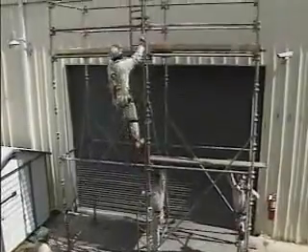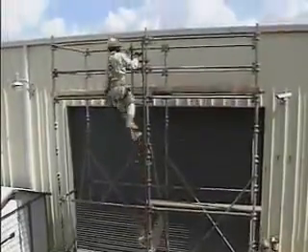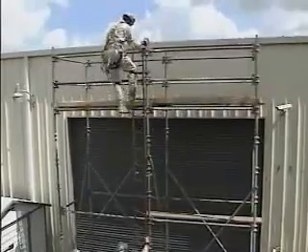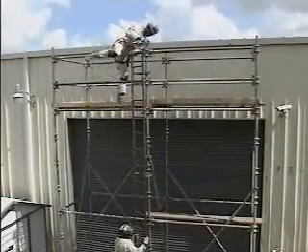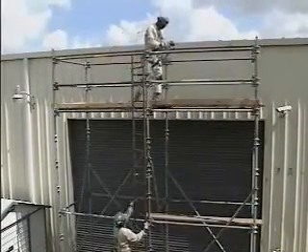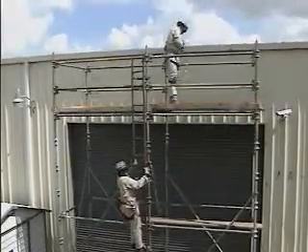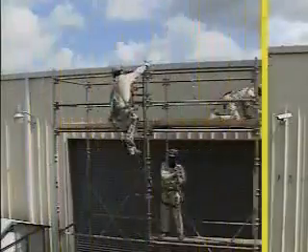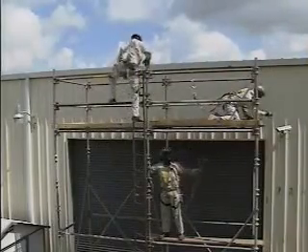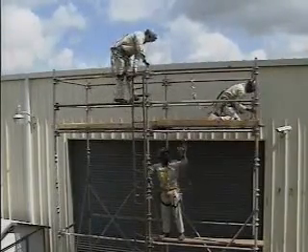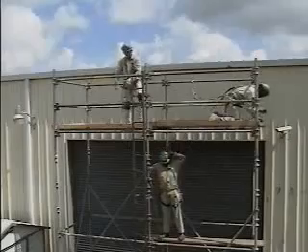For example, always use both hands when you're climbing a scaffold ladder, and be careful when you're entering or leaving the work platform. Don't jump onto the scaffold flooring, since there's always the possibility that a plank could be loose or break. Also, avoid overloading a scaffold. Always follow the manufacturer's recommendations about safe working load limits.